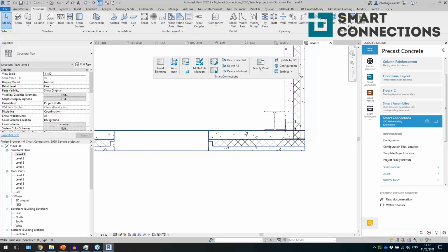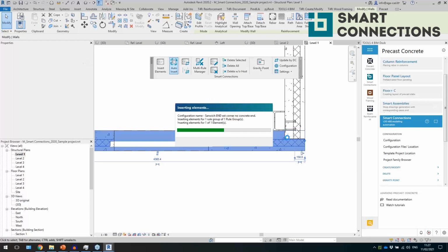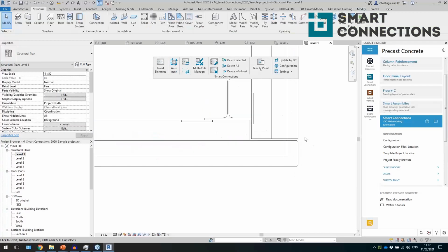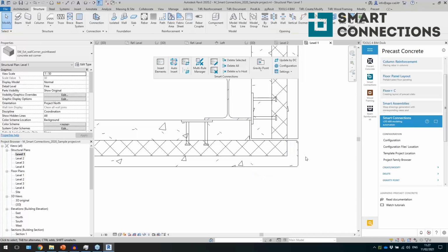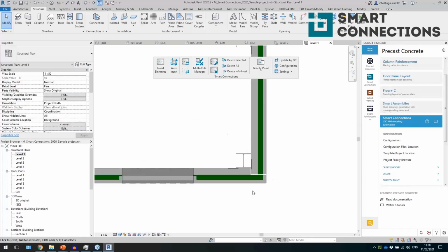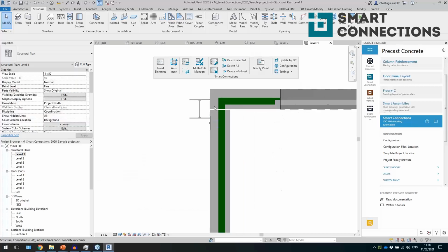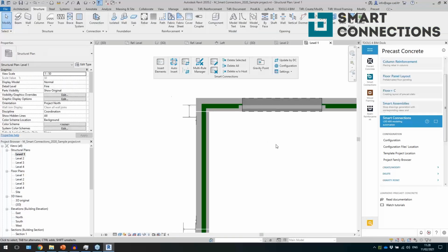These walls are just overlapping like that, and then by using smart connections, I'm placing a couple of families here. One family is cutting my wall end, and another one is cutting, but at the same time it's placing some concrete element and is joining together with the wall. So I get this kind of nice shape with a connection of the wall. And in another corner, the same situation, I just placed some family for the insulation and some family for the concrete.